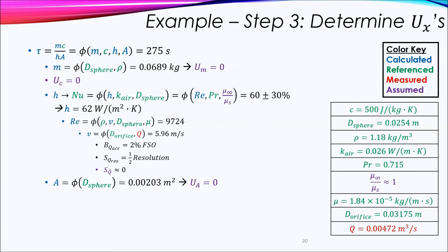So the measured value can be broken up into three components of possible sources of uncertainty. So the rotameter is quoted to have an accuracy of 2% FSO, and the resolution is always half of one of those tick marks. And then the random uncertainty we're going to assume is 0 because you're waiting until the measurement is approximately steady state and the fluctuations are smaller than your resolution marks, and so you are not able to measure that random fluctuation.